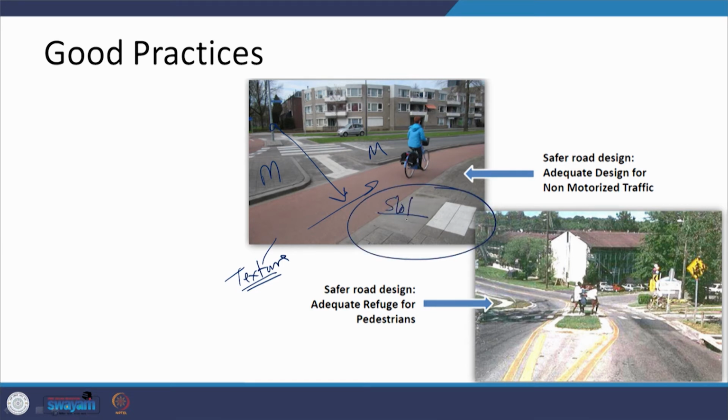There is a slope here, and then there is a flat surface on that side, and along with that there are tactile tiles being provided. So, this defines it. The same tactile tiles are also being provided here, so that anybody who has this type of disability can find the way and can cross at this particular location. So, this is another way of universal accessible design being provided.